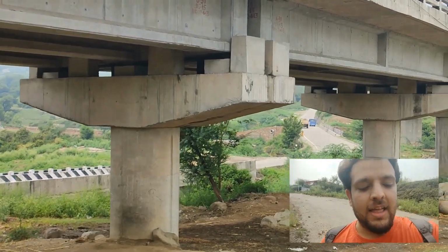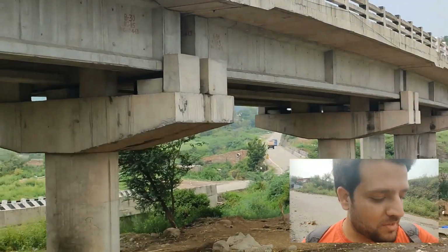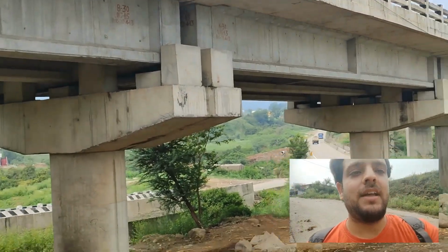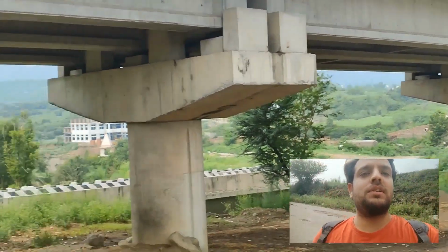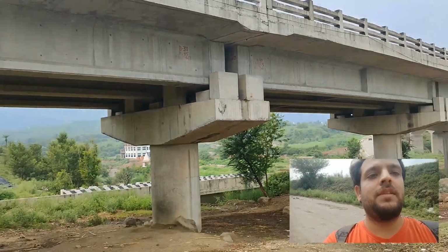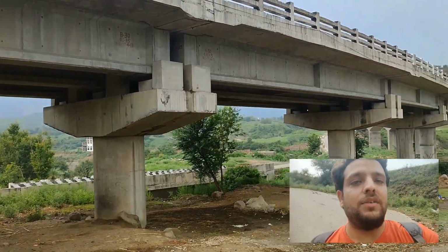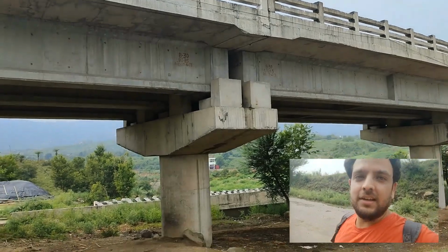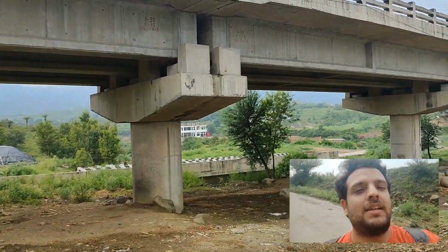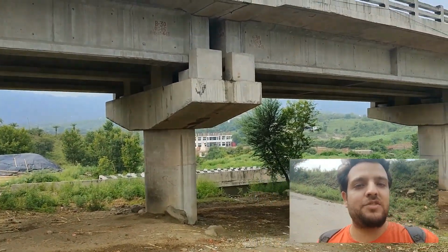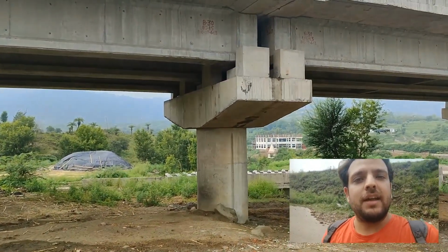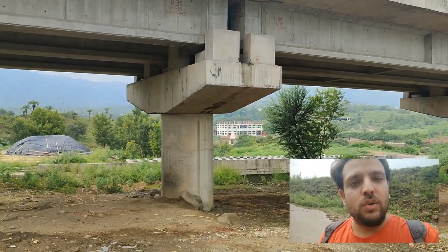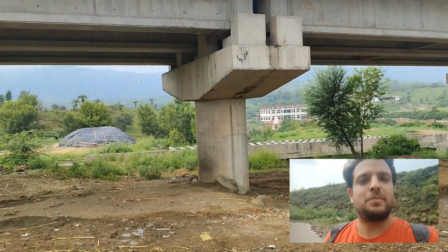Another force for which this cantilever pier cap is checked is torsion. So you may be wondering how torsion can be introduced in this system. Please note that even if the spans on both the sides are equal, there are high chances that the traffic movement on the left span may be different than the traffic movement on the right span, or the traffic on the left span is fully loaded or one of the spans is partially loaded.